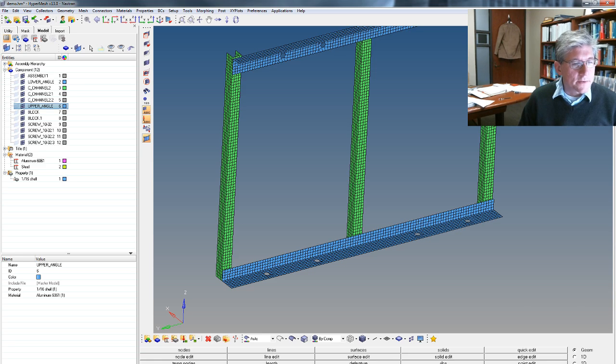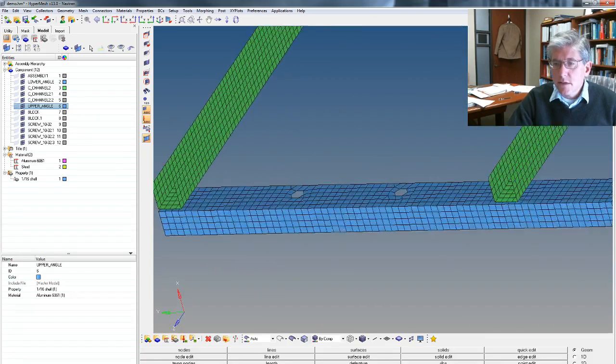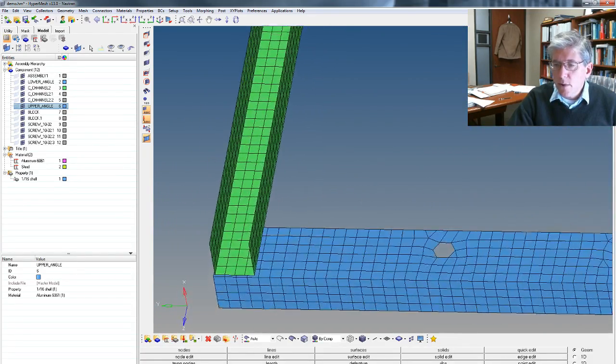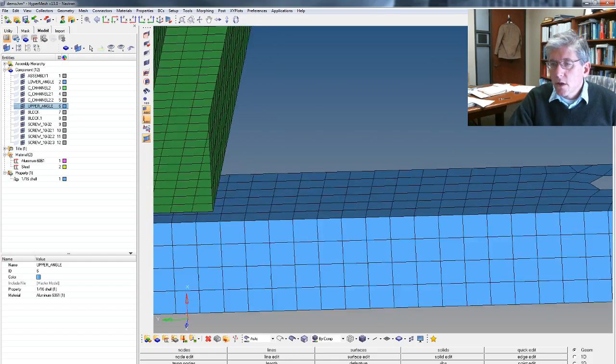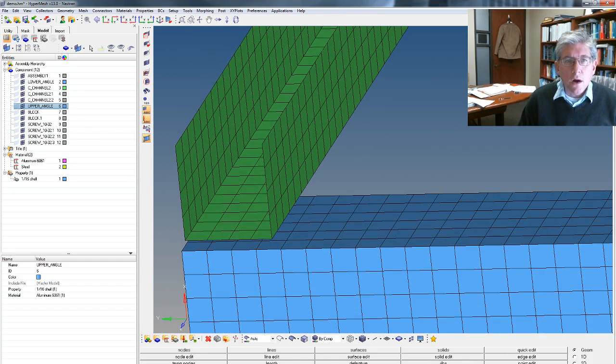And so, as I mentioned briefly in class, there's several ways that we can do the welds, but a simple way is to sort of approximate the connection with RBE2 elements, or you can even span some more with RBE3s, but like I said, I think the one RBE2 is kind of not a bad idea because, if you model all the weld material, it's probably stiffer than it really is.